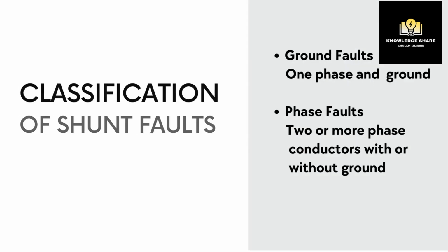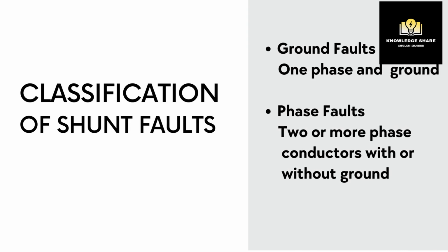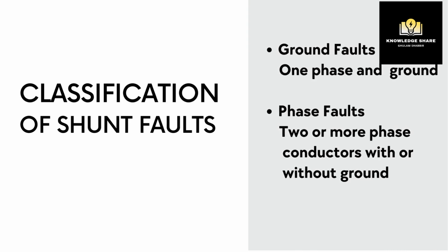Now we see the classification of the shunt faults. Those faults which involve only one phase and ground are called ground faults, while the faults involving two or more phase conductors with or without ground are called phase faults.